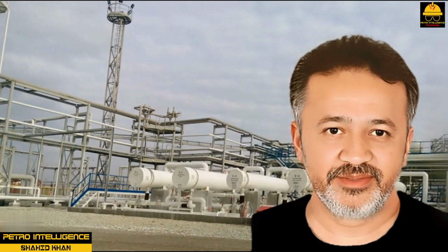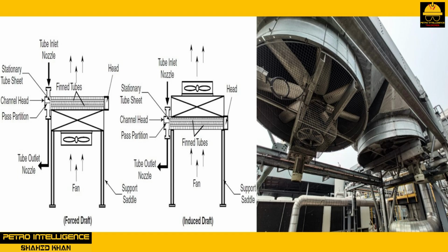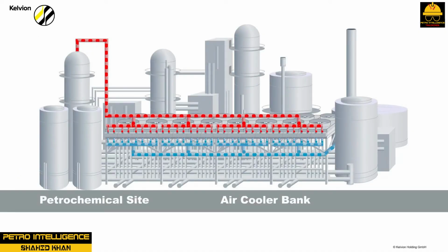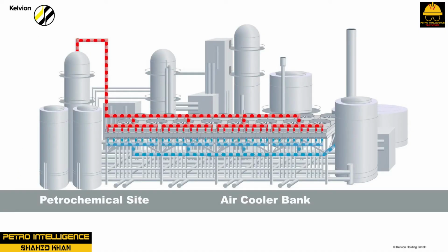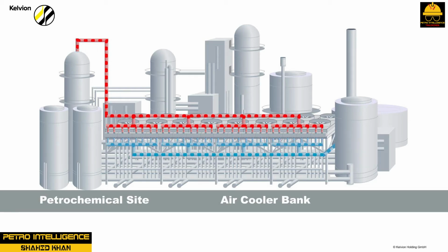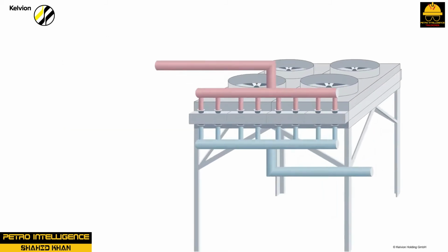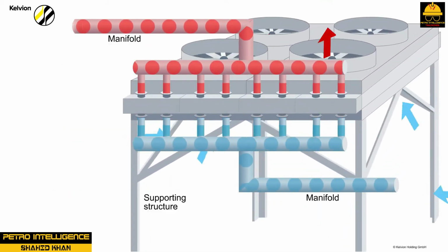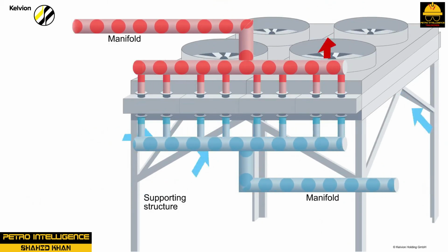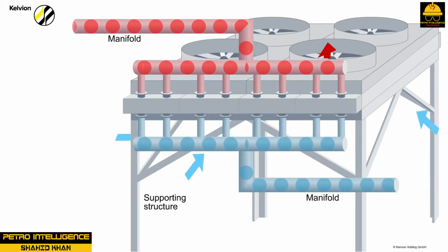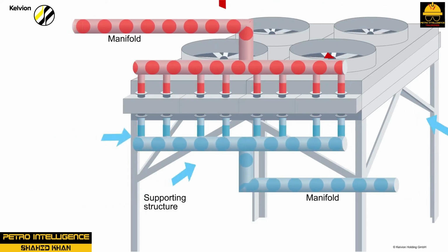Air-cooled heat exchangers. A different approach to heat transfer occurs in the fin fan or air-cooled heat exchanger. Air-cooled heat exchangers provide a structured matrix of plane or fin tubes connected to an inlet and return header as shown in picture. Air is used as the outside medium to transfer heat away from the tubes. Fans are used in a variety of arrangements to apply forced convection for heat transfer coefficients. Fans can be mounted above or below the tubes in forced draft or induced draft arrangements. Tubes can be installed vertically or horizontally.